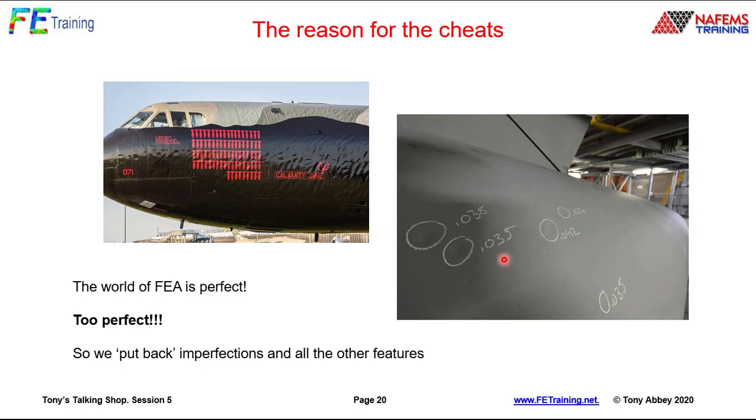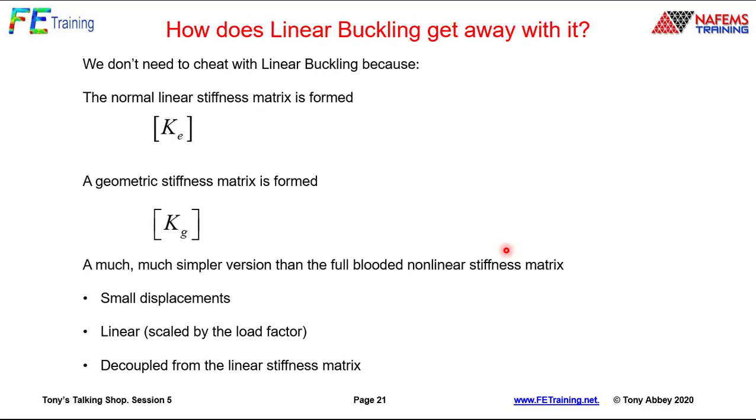And then certainly a lot of work I've done, we get little dents and things happening from either tools, bird strikes, rain, hail, things like that. This is the back end of an aircraft fuselage, and we want to put back these local imperfections and other features. This is where we'll be applying a point load to get maybe a little dimple in there with a particular shape. And again, we've got some measurements in here of the maximum depth, so maybe we can actually put those in there more directly. So sometimes it's overall, sometimes it's more specific kinds of values we're putting in.